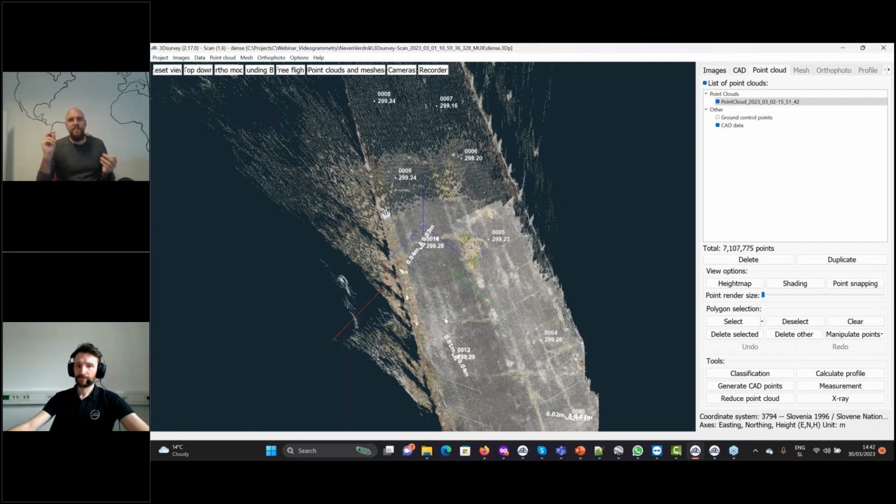But that accuracy in absolute terms might be slightly lower. So I know I signalized a point outside and measured it a few times with the GPS, and I know that sometimes the GPS will say that you have a centimeter or 2 accuracy, but my GPS position will be off by a few centimeters.